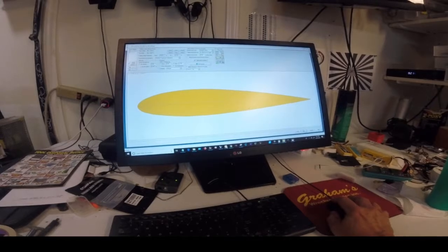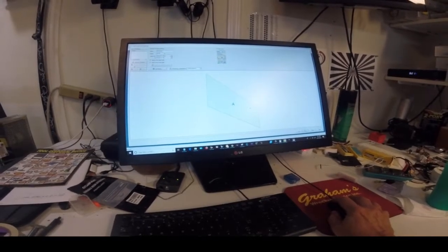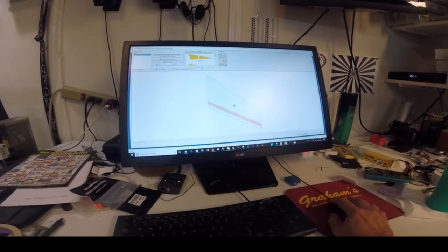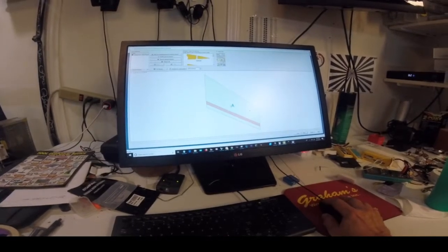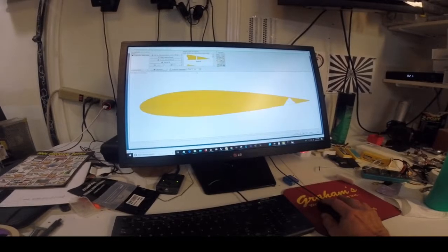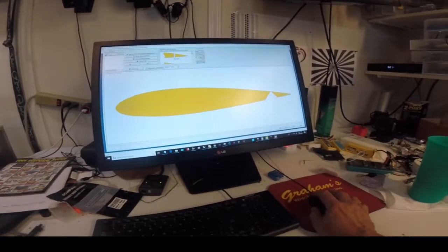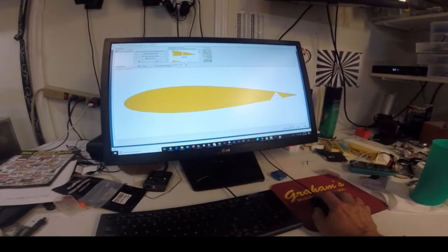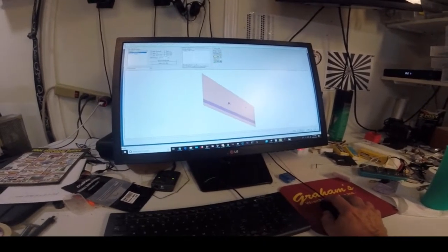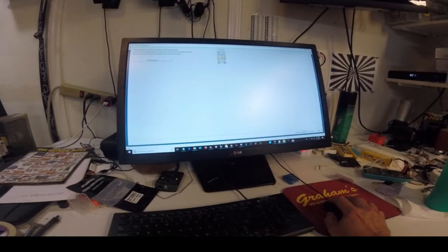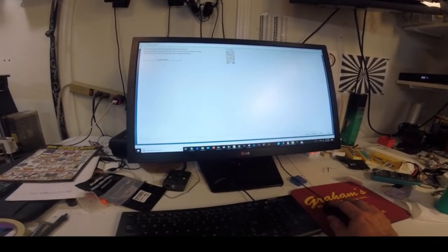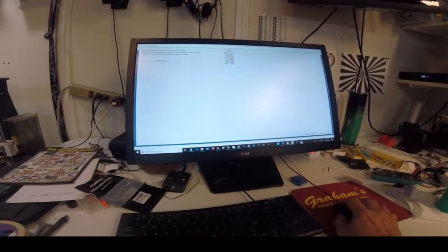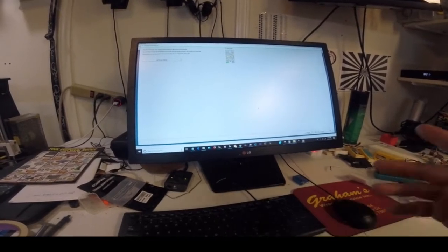And this is actually a very good program. Anyway, it walks you all the way through, and you set things in like the cutouts we're doing to get rid of the ailerons. Here's one here, where you can see that we've got it set in there, and it will actually cut that out. And then once you get all that set, you go through and you apply the G-code strategy. It actually makes the G-code.